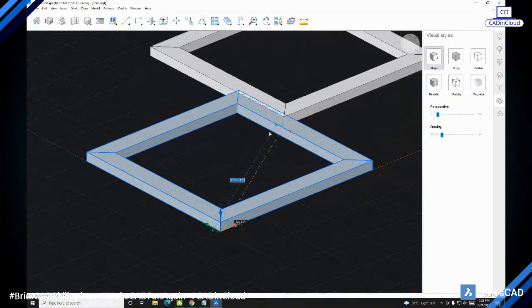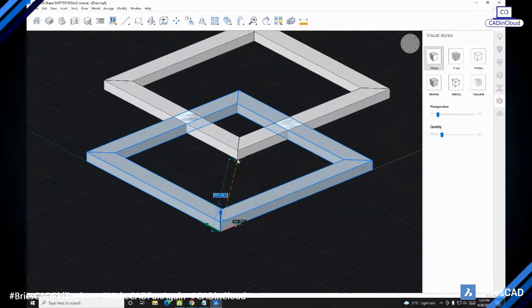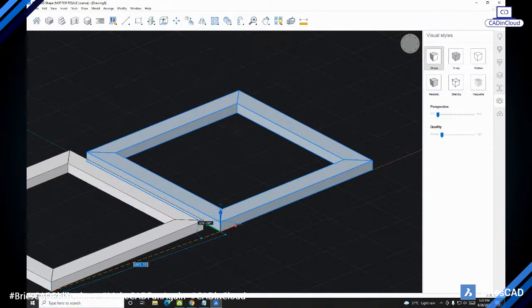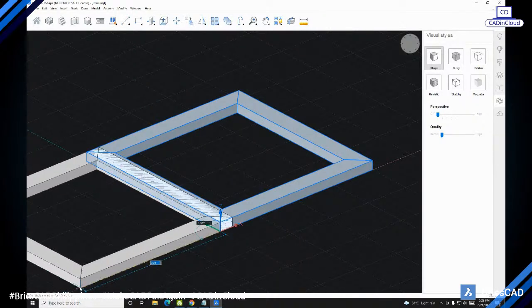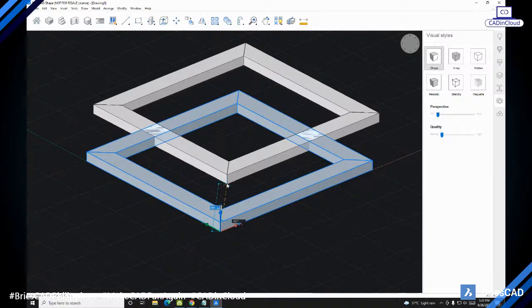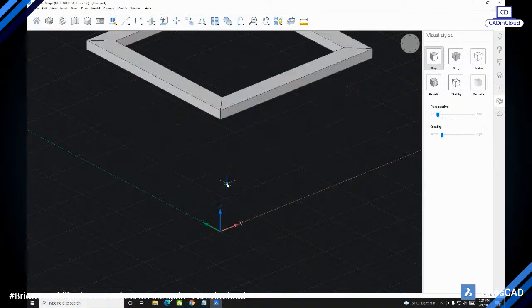Then after that, I am going to put a value. As I said, we don't have movement along X, Y, so we are going to put zero on the X and Y, then we will have a value only on the Z axis. If you notice on your command line, the value for the displacement that it's requiring is three values: X, Y, and Z. X comes first, then Y comes second, then Z comes third. So we're going to type 0, 0, 600 for the displacement. Okay, accept.